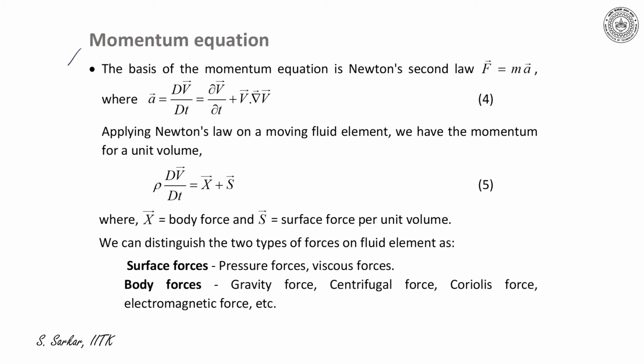Let me discuss in brief the momentum equation. The basis of the momentum equation is Newton's second law, that is F equal to m times a. m is the mass of a fluid particle and a is the acceleration, which can be given by DV/Dt, the total acceleration, equal to ∂V/∂t, the local acceleration, plus V·∇V, the convective acceleration.